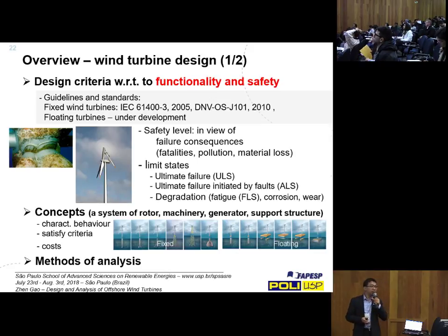So basically, we design a wind turbine to fulfill its functionality, that is, to generate electricity in an efficient way. And then we also have to design the structural part of the turbine so that it can survive the design lifetime, typically 25 years. This refers to the ultimate limit state design, for the largest possible loads during the lifetime. And also, it's a dynamic machine, so you have to design for fatigue issues.